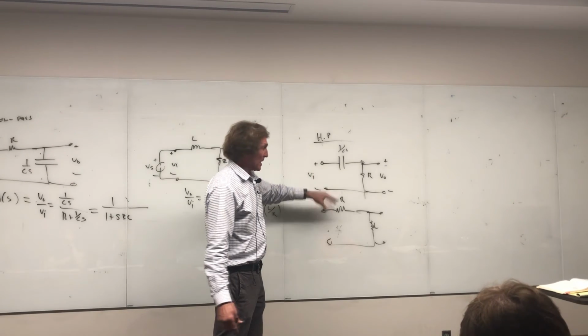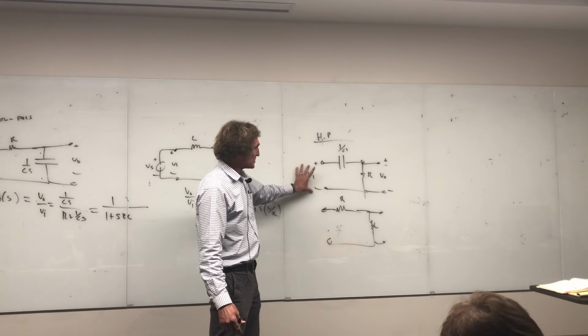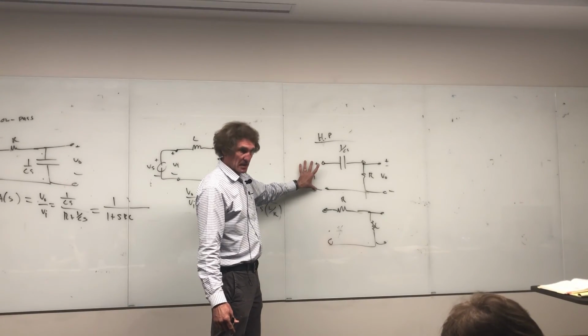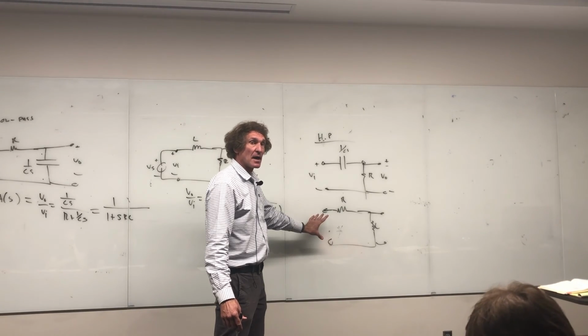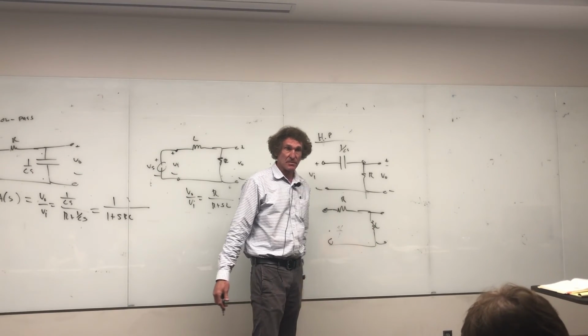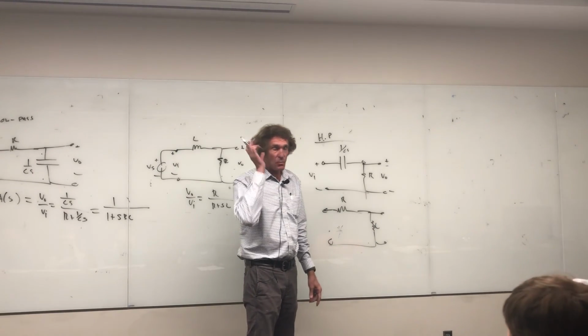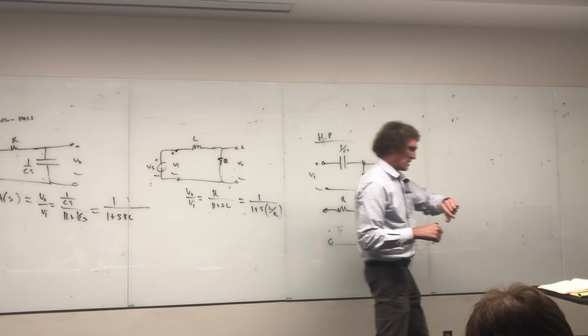All right? Now, at high frequencies, though, what happens? At high frequencies, this looks like R, doesn't it? The input impedance, what about this one at high frequencies? It's infinite, right? Because this goes to infinity at high frequencies, right? Now, the truth is there's more to this because there's loads attached, but I didn't have time to get into that. And right now I'm about out of time, too.